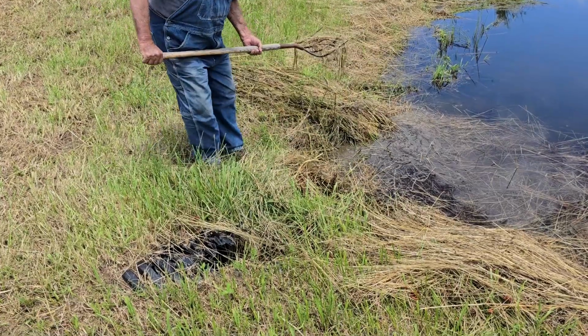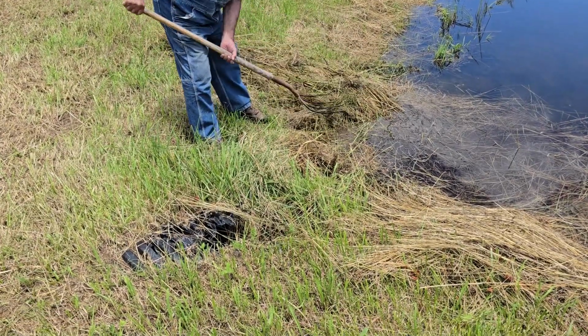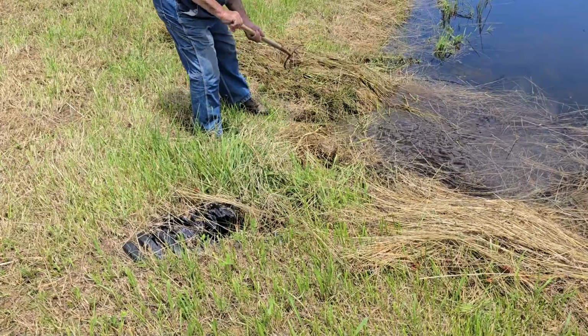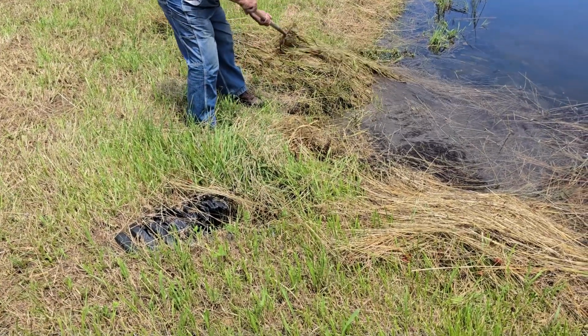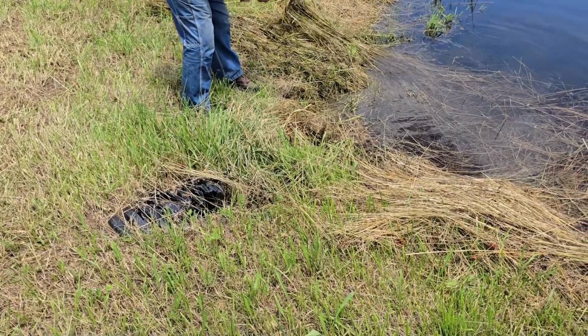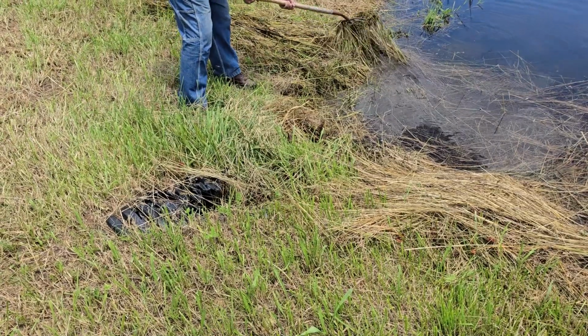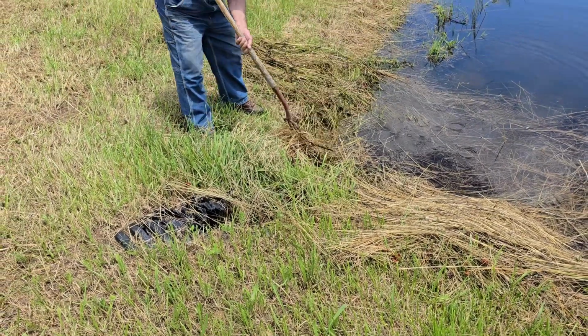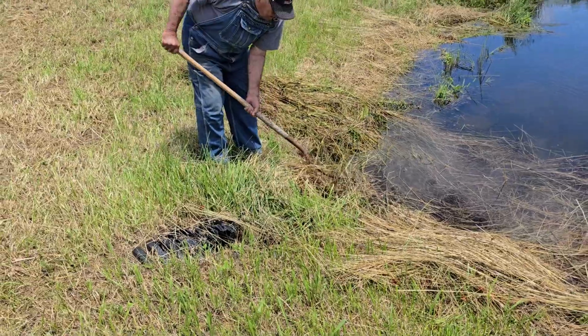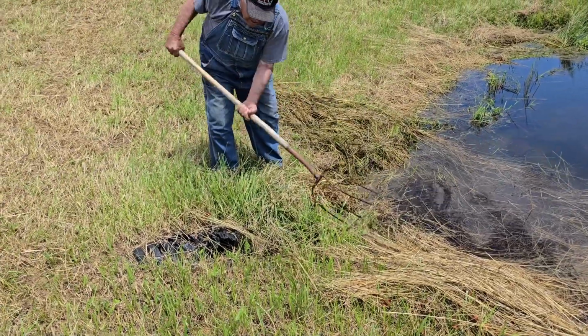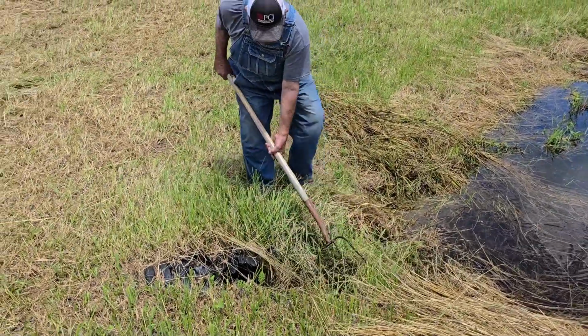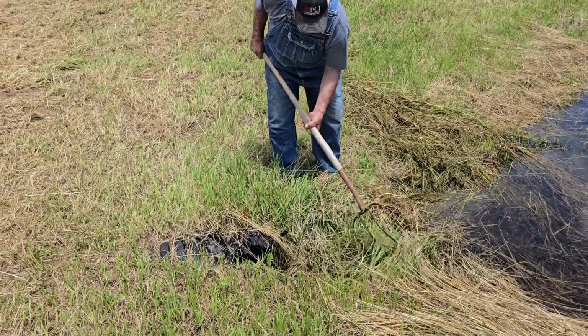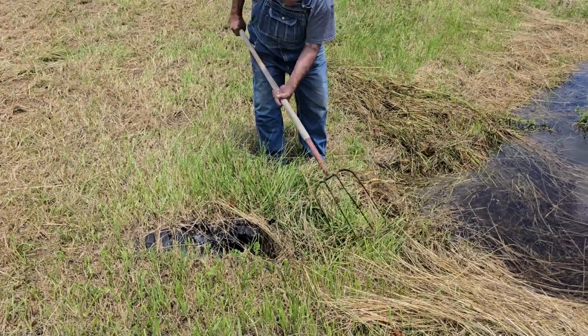Wayne uses a pitchfork to remove vegetation that could block the entrance to the overflow pipe. This pipe carries water through the dam. It's surprising how only a few plants can block water from entering the pipe. Here he's removing the grass that collected in front of the pipe after he cut and baled the hay that was surrounding the pond. You can see where his batwing mower damaged the inlet to the plastic overflow pipe.